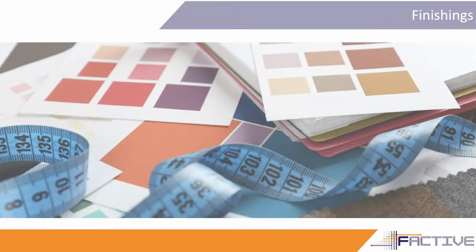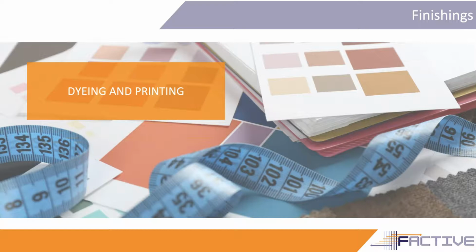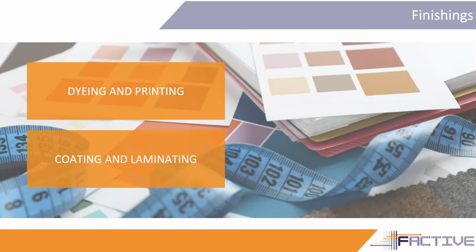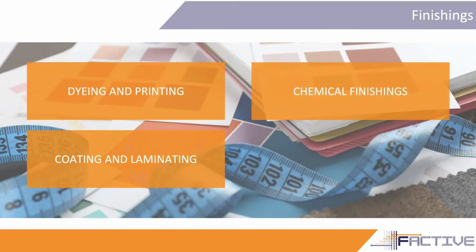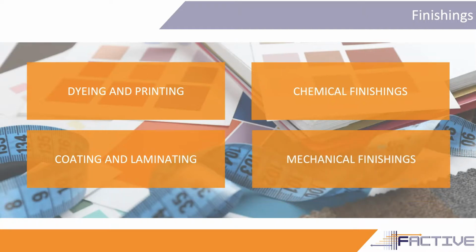A fabric finish is applied to a fabric once it has been made to improve its appearance, feel or other properties. Dyeing and printing give color to the fabric. Coating and laminating deposit a resin or a film and bond it on the fabric. Chemical finishings, such as bleaching or antibacterial, use chemicals to achieve a desired fabric property. Physical finishings, such as stabilizing or napping, achieve a specific characteristic through mechanical processes.